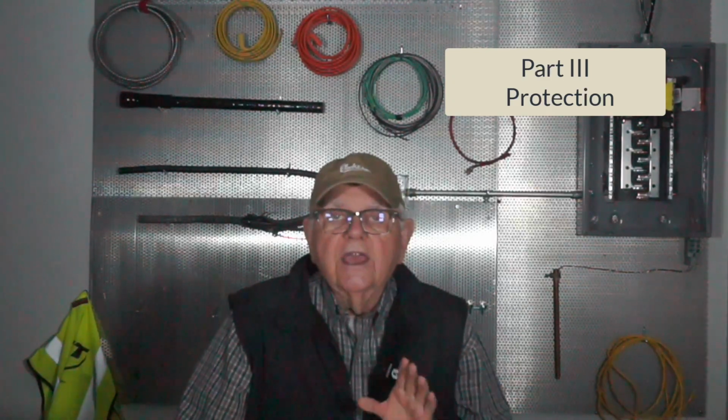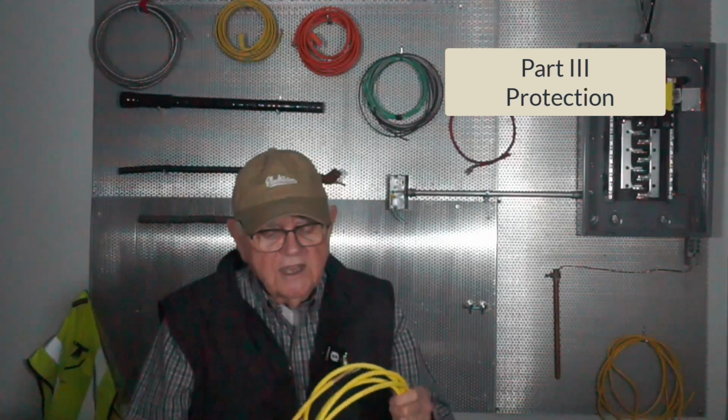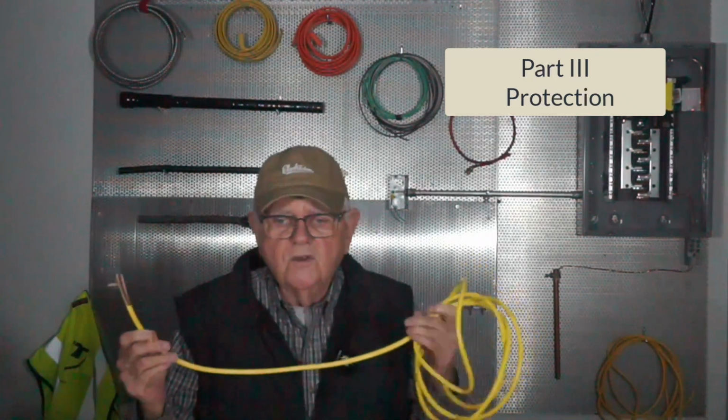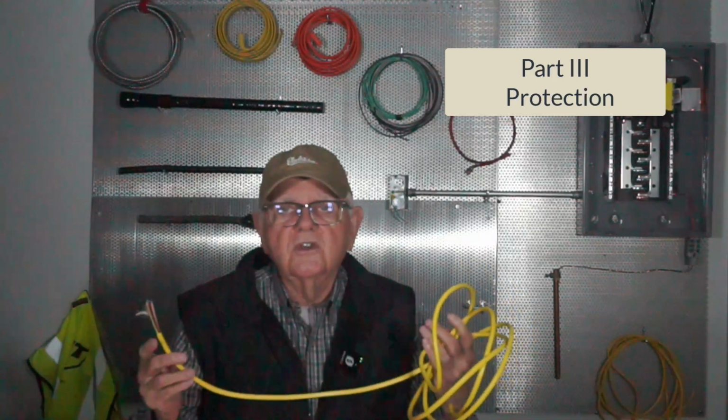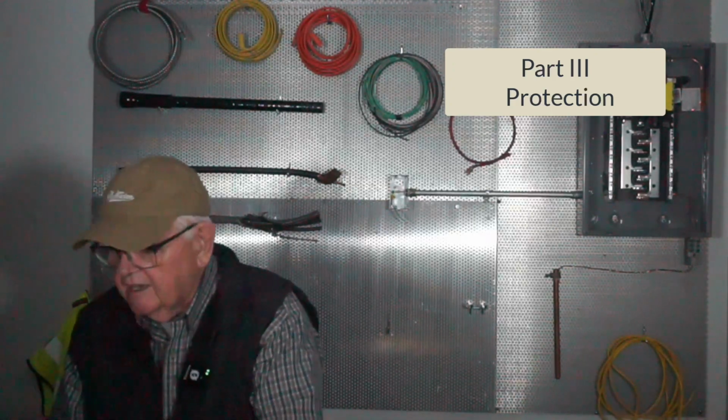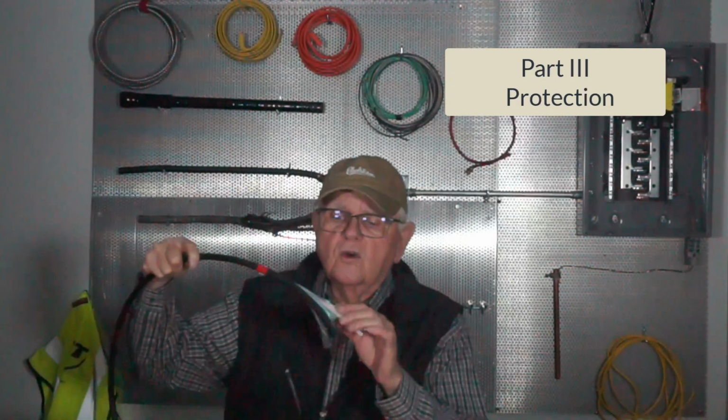Part 3 gets into protection. And it's a very short Part 3, but it talks about grounding and bonding requirements. So if you think about it, a lot of fiber optic cable, we said this was non-conductive, OFN type fiber optics. So if it's non-conductive, there's nothing to ground here. But on the other hand, this particular cable has a corrugated metal sheath wrapped around it, as we saw in the close-ups, and so that's metal.